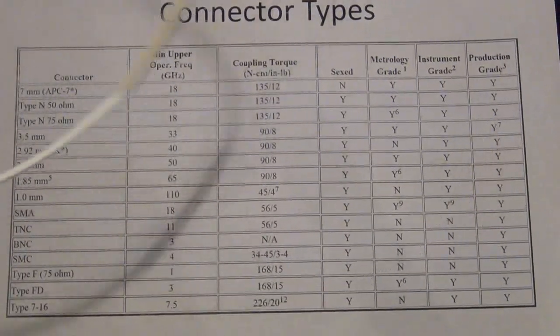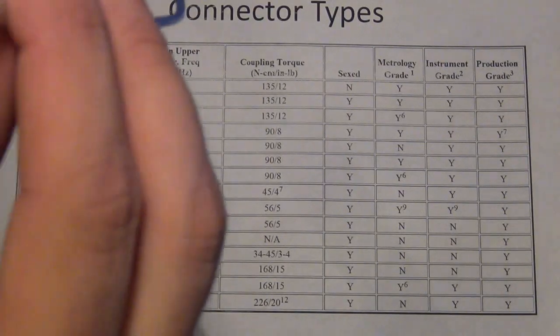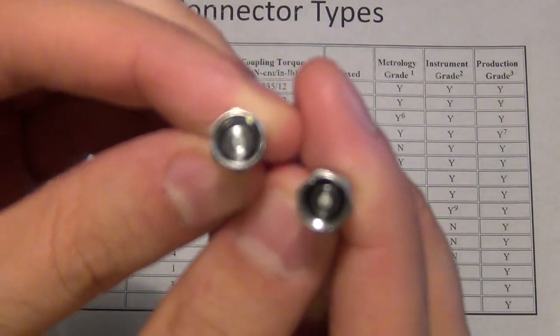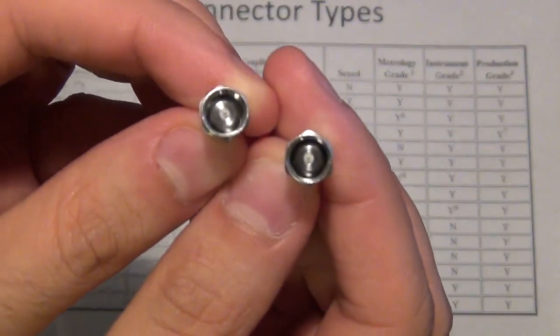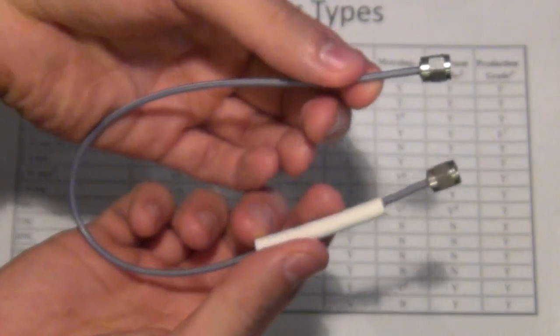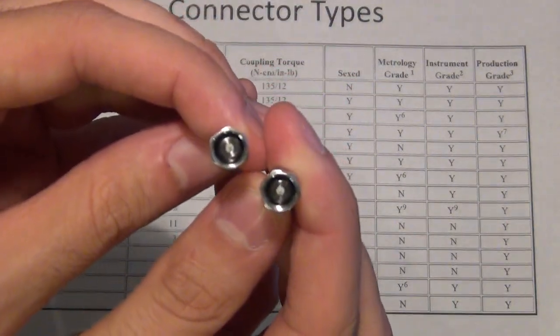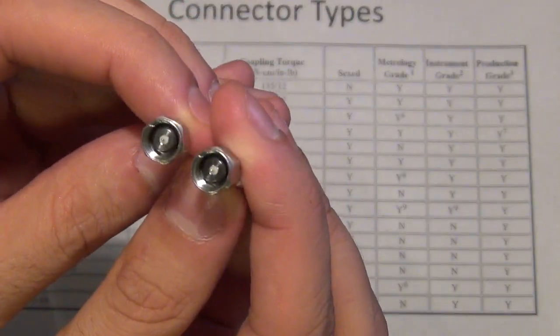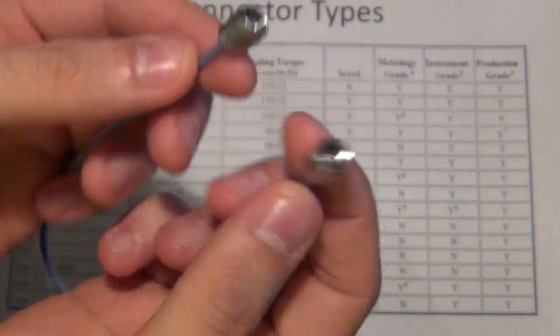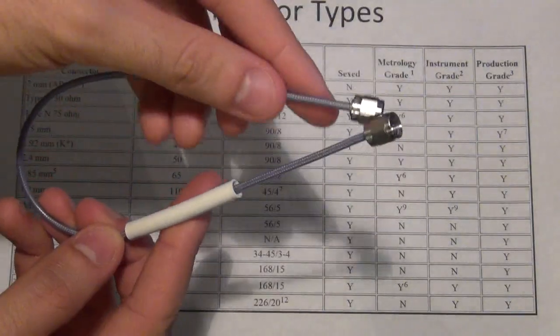But if you go to instrument grade cables where people don't use air dielectric, you can actually get a different material dielectric. I'm not sure what this one is. It could be Teflon, but I'm not 100% sure. This is actually a V cable. This is a cable that will work all the way up to 67 gigahertz, but it doesn't have an air dielectric connector. Instead, it uses some other dielectric material, but it is a V connector. So this is, for example, a good day-to-day use cable. And just because it's day-to-day use doesn't mean it's cheap.